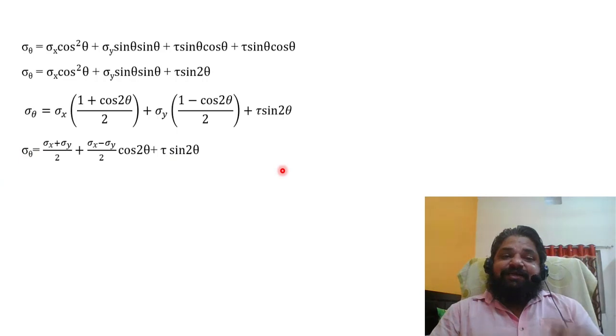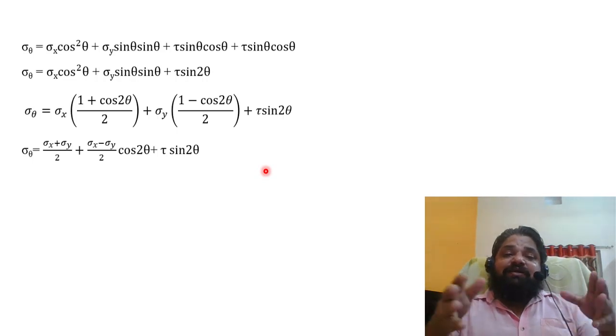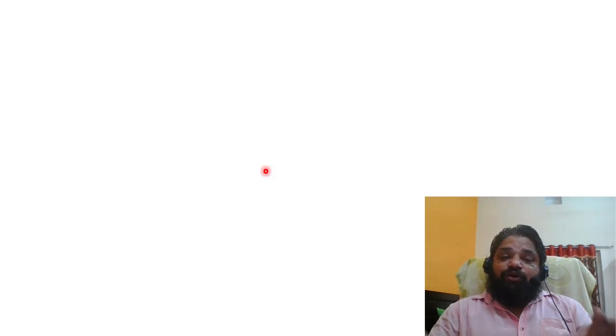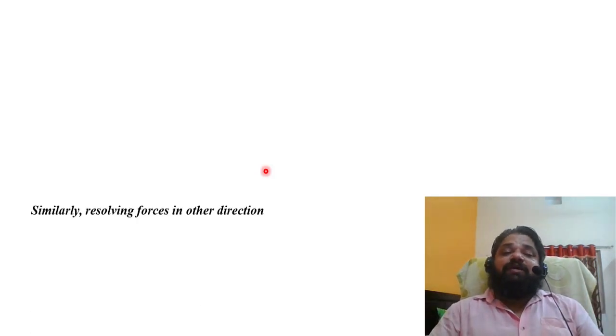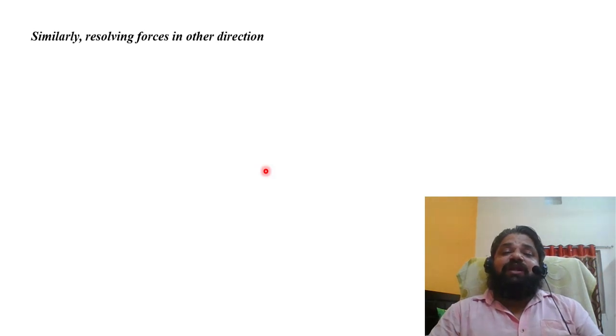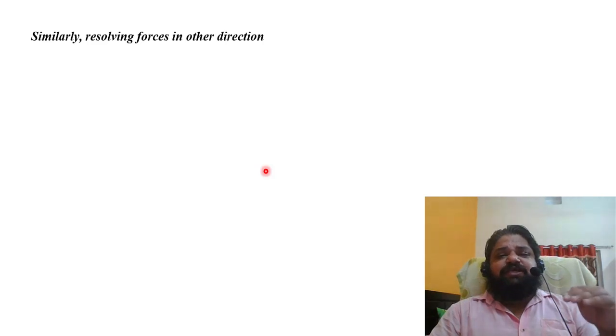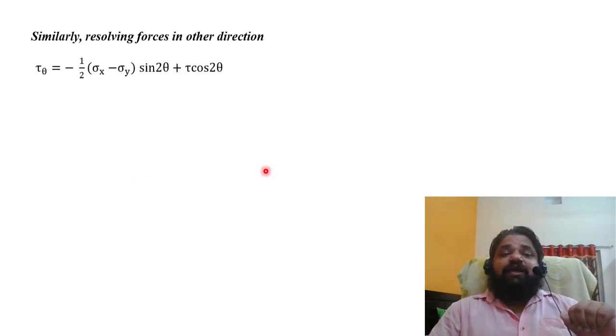It is nothing but the resultant stress that develops on a particular element by applying a combination or a group of stresses onto it. And we know whenever we apply a load, a combination of stresses will develop. If a combination of stresses develops, then how do we handle it? This is what the principal stress gives us: the resultant stresses in their corresponding planes.